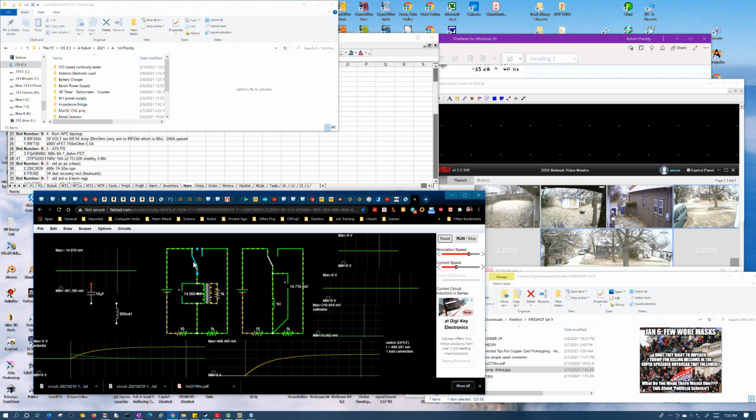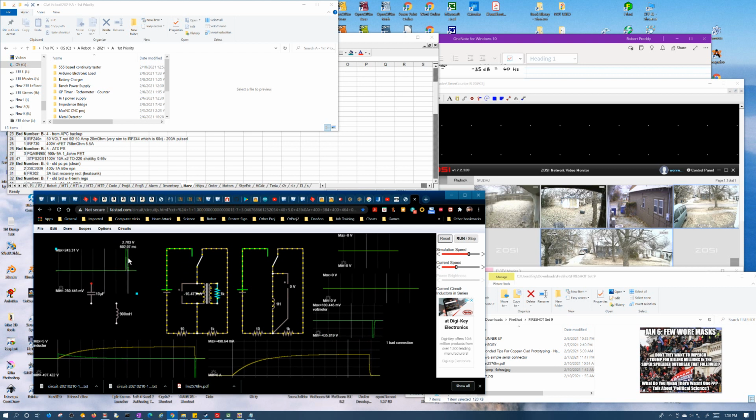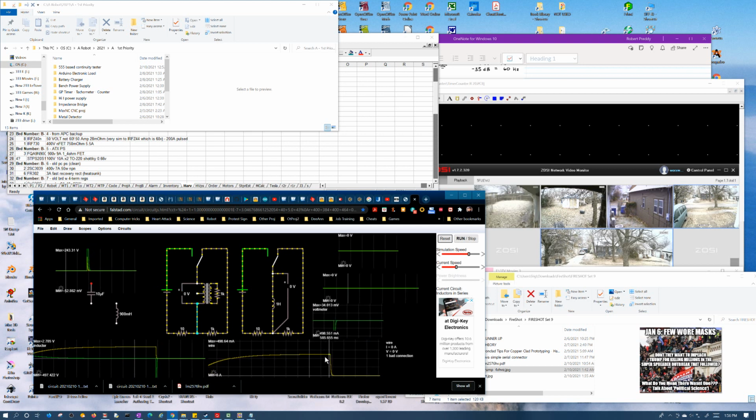Sufficiently charged. Alright, let's hit it. Okay, now we get like a 200 volt spike over here. Remember before we weren't getting any kind of high voltage spike, and here we're getting a 400 volt spike, but it's much more drawn out. Instead of being a little chirp, it's now a pretty wide band. And again, it's trying to maintain that ½ amp of current, and here's the same thing. We get this spike drawn out.